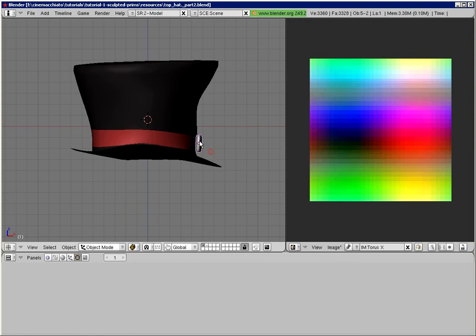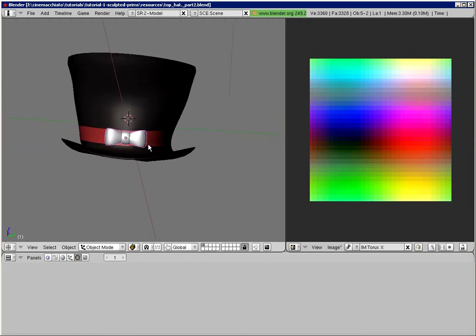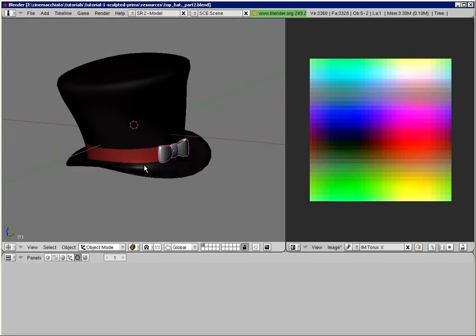Okay, we have eventually created a satisfying shape for the hat. It is made out of 3 sculpties instead of only 1. And this is the moment where we start getting into real trouble. How can we transfer the 3 sculpties into Second Life? And how can we keep their relative positions, sizes, and rotations intact? Now there is another nice trick, which is again introduced by primstar. You can automate the setup of your sculpties in Second Life, but we need to do some preparations beforehand.